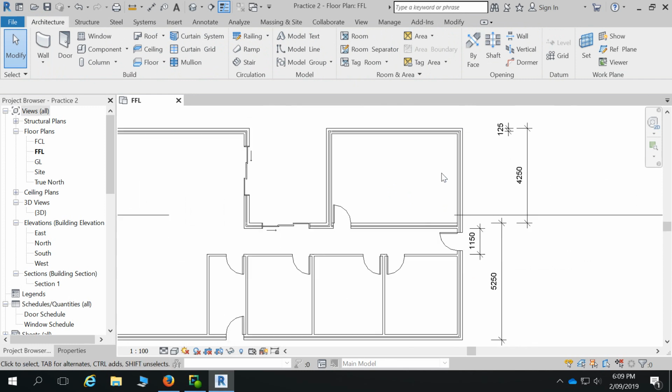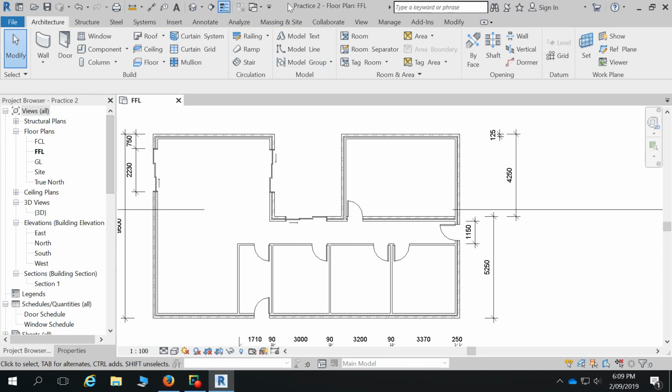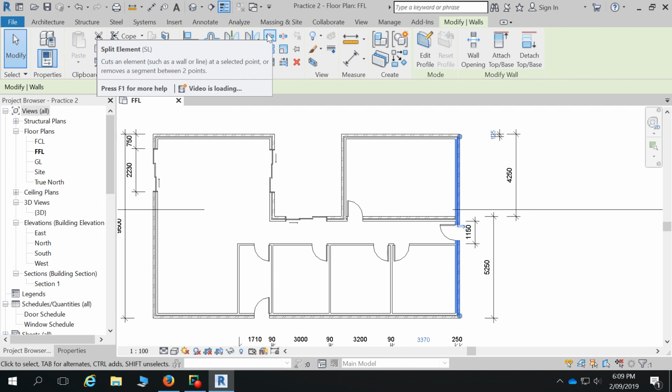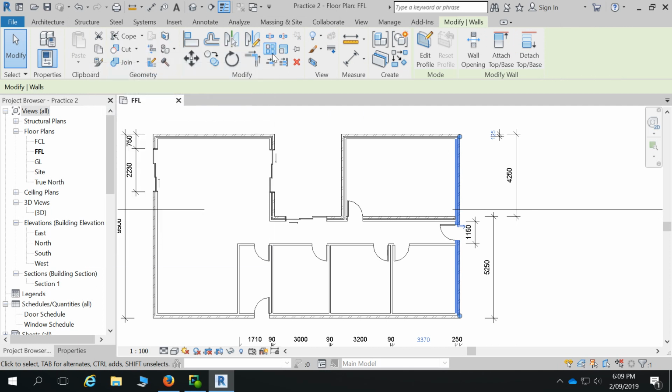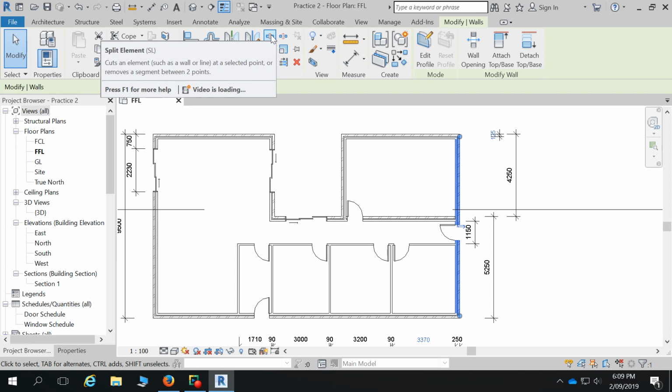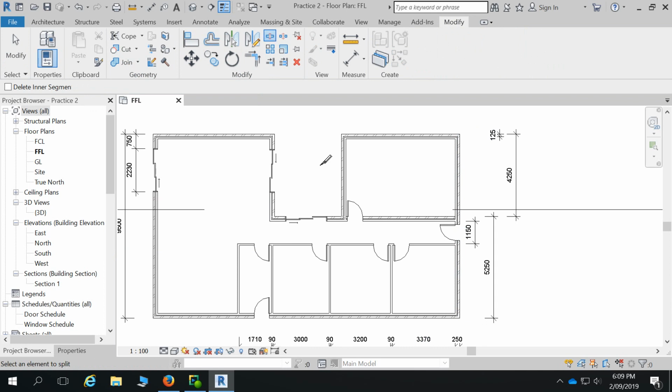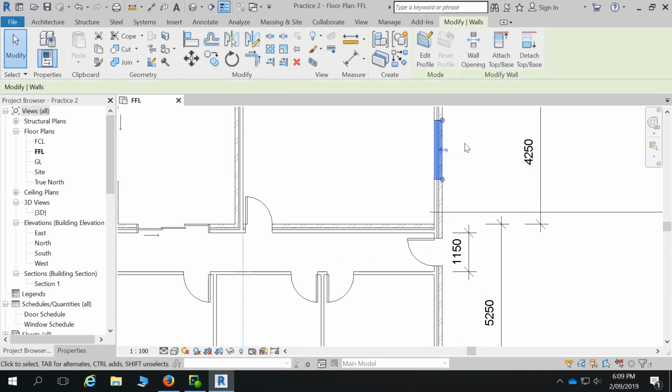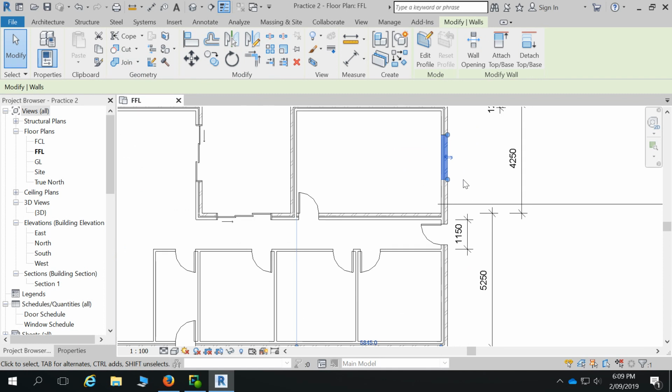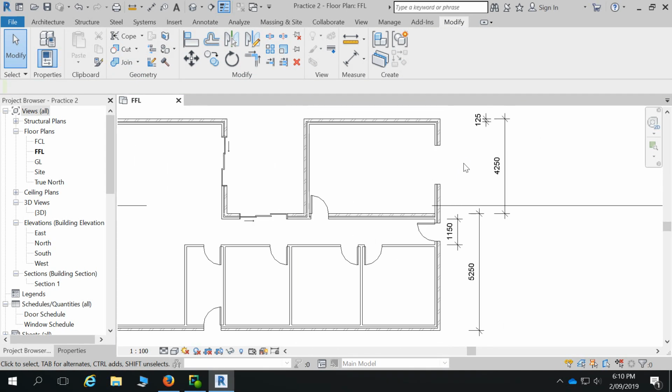And then to make that break in there, like you said, that was really good. To actually modify that, use the split tool. Okay, so split the element. You've got the choice of splitting with a gap or splitting. What I tend to do if I'm going to delete a section is split the wall twice. Just once and twice, it doesn't matter what portion I've got, and then that middle becomes a separate little wall, and then I can just hit the delete button. So once you've got that section deleted,